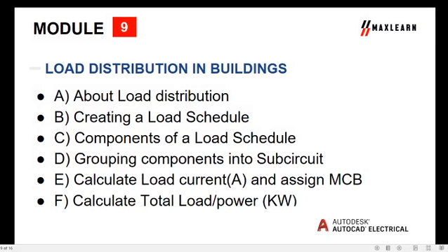Today we'll be treating Module 9 and our topic is load distribution in buildings. What it involves is that we're teaching about load distribution, creating a load schedule, components of a load schedule, grouping components into subcircuits, calculating the load current in amperes, and we'll be assigning them to the MCB, that's the miniature circuit breaker. Again, we'll be calculating the total load and power in the whole building in kilowatts.